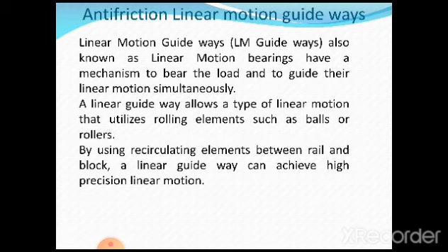Basically, the aim is to reduce the friction to almost zero, because the coefficient of friction is the main drawback in the case of frictional guideways. Such a difficulty can be prevented by the application of linear motion guideways or linear motion bearings.